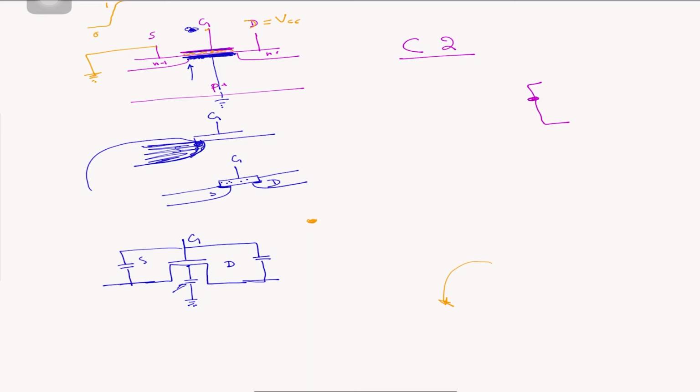So this part of the gate capacitance is not constant, because once the current starts flowing, you don't have this anymore. But as soon as we keep increasing the gate voltage more, a pinch-off region happens. So the region looks like this.